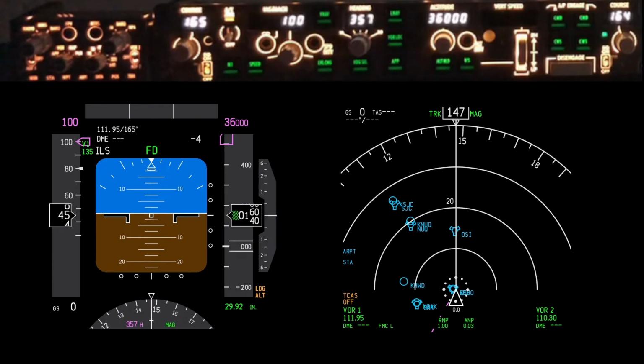You'll notice on the left-hand side in our flight display, the V speeds on the ticker have been added based on the programming that we've done so far in the flight management computer. Also, the FMC gave us a V2 speed of 147, so we're going to set our indicated airspeed on the MCP to 147, and we'll come back and adjust our course for the runway that we're taking off on, and also the heading, once we're done programming the rest of the flight into the FMC.